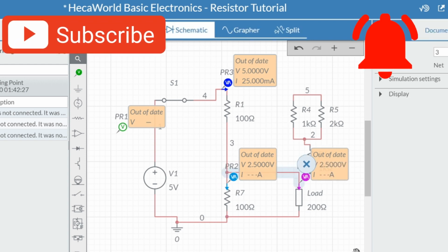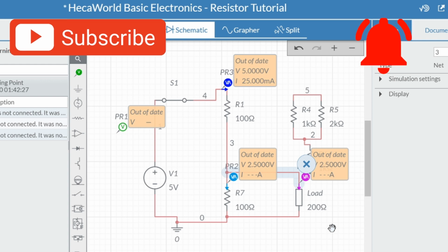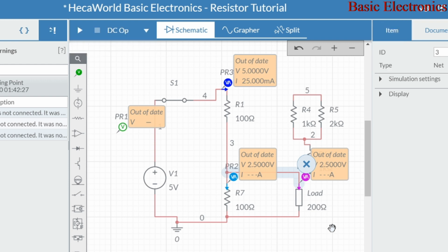Okay, before we do that, I want you to know that when resistors are in parallel, the equivalent resistance of that path tends towards the lesser of the two. If there are 3 or more, then it will tend towards the least value in the system. So the equivalent resistance here will be less. At best, it will be around 100, but it will be less than 100. And when they're in series, the equivalent will tend towards the bigger of the two.